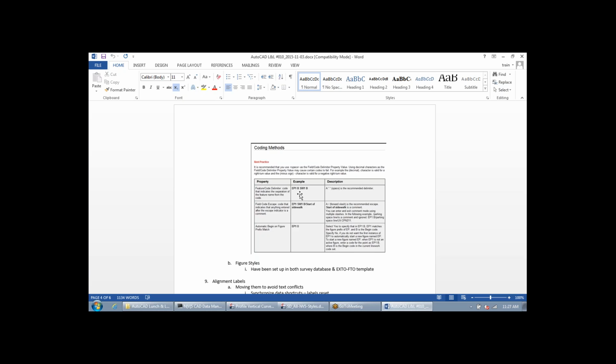I will say the one issue that I've run into with the all points in the survey database is with point stringing. When you combine all those stringings together in your CSV, typically our surveyors, in each individual CSV or each time they go to the field, will go EP1, and then a week later when they go out and start stringing again, they'll go EP1 again.